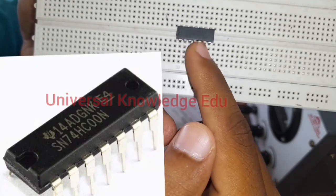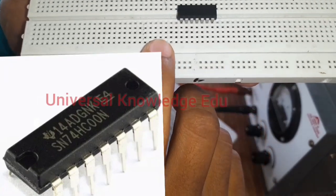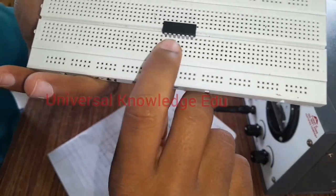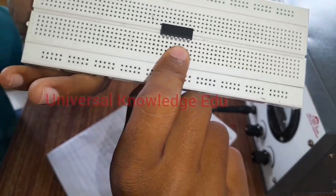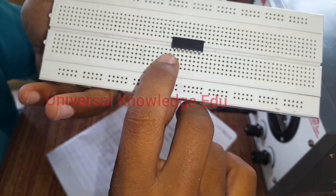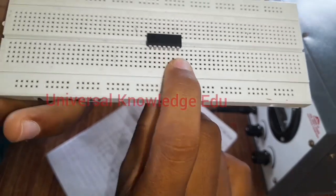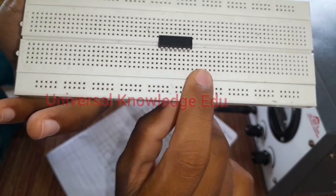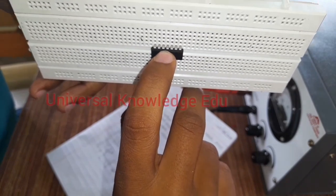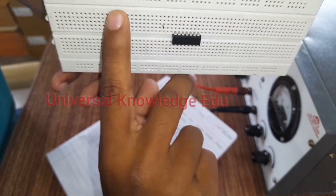Okay, this IC has 14 pins, 7 pins on one side and another 7 pins on the other side. These 14 pins give us 4 logic gates: 3 pins make one logic gate, another 3 make another logic gate, the last 7th pin is ground, and again 3 pins make another logic gate, and another 3 make the last logic gate. This 14th pin is plus VCC, which supplies the positive current.